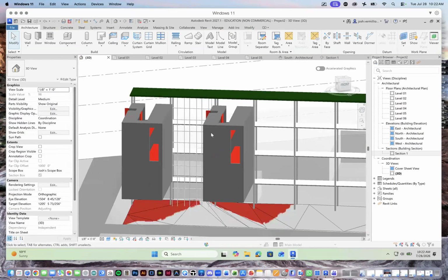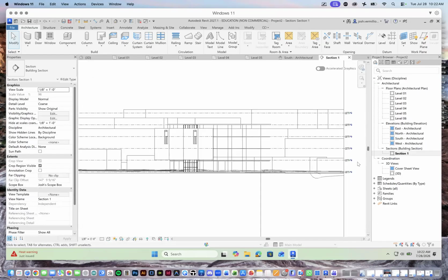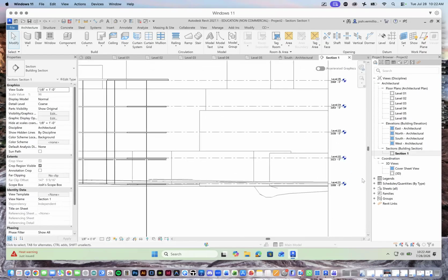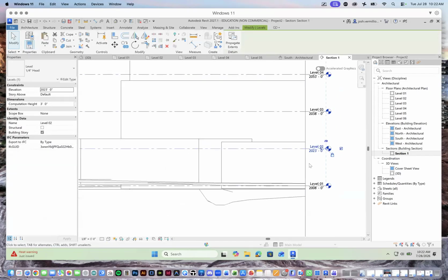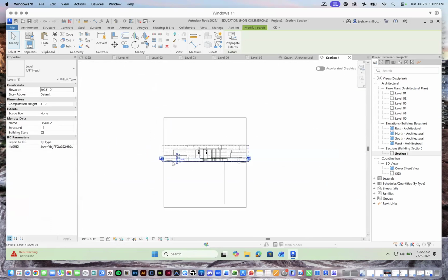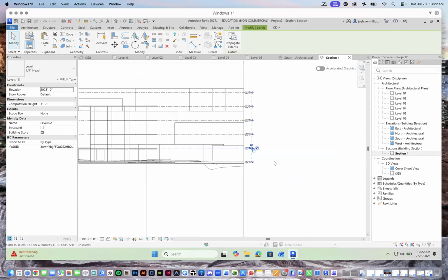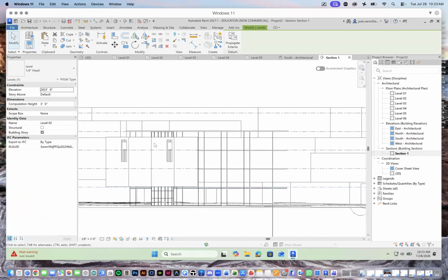All right. Should we also talk about stairs and elevators while we're here? I think we should. So I have a floor to floor, and that's a big deal when it comes to thinking about stairs. Your floor to floors are what's going to dictate quite a bit about your stairs. If I go to level 2, I can see that I am 15 feet. I've tried to stick to 15 feet floor to floor here, even though the ground is kind of sloped.